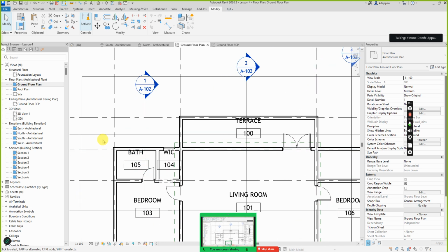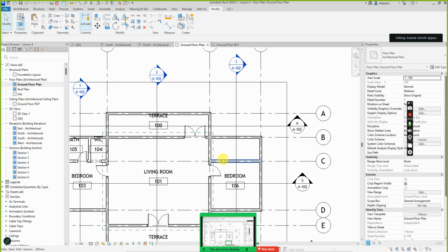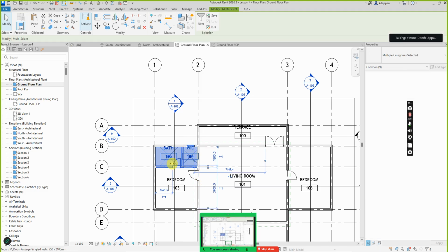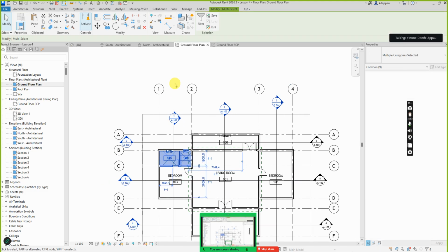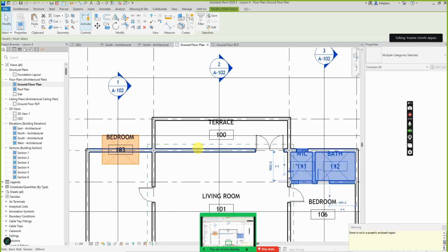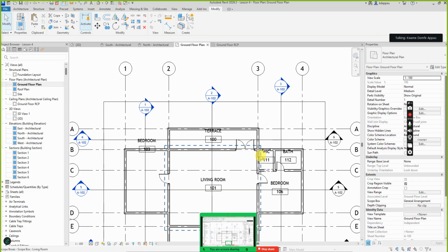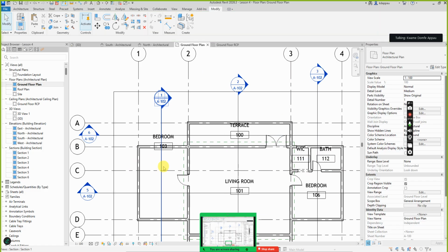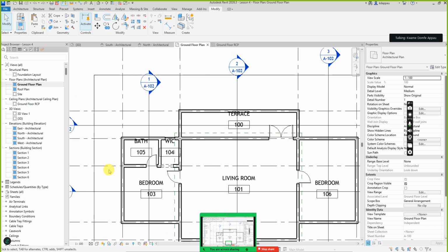So I can select this whole thing again. So what I'll do is that this time I'll also delete this one also. So I'll just select this whole one, everything in this corner here. So I've selected the whole thing. Then I'll go to mirror, and then mirror it using this one as a center. And then mirror it this way. So a copy will be created here. When I was mirroring, I still forgot to mirror the copy. So Control Z, undo.